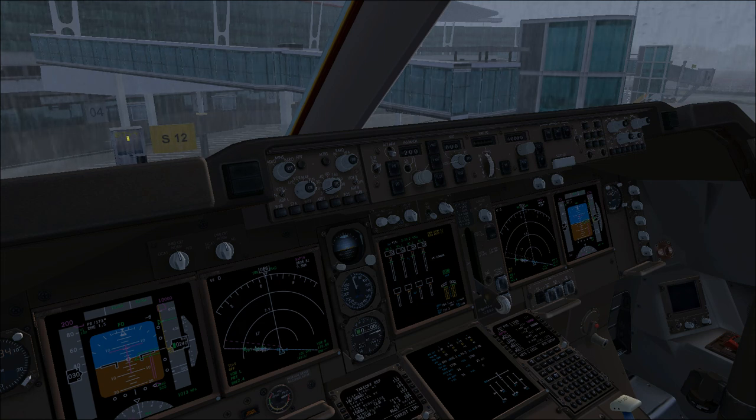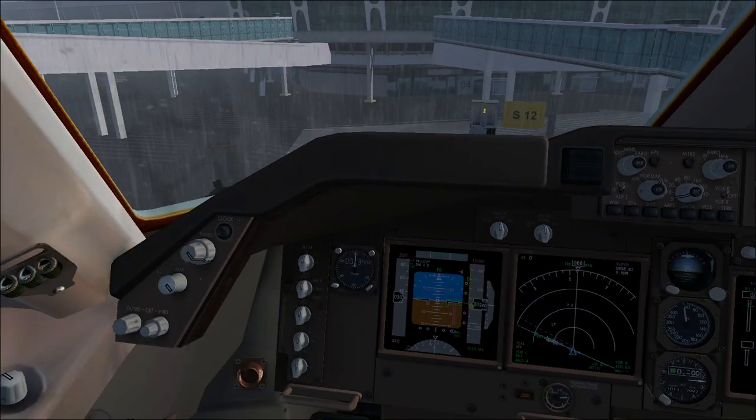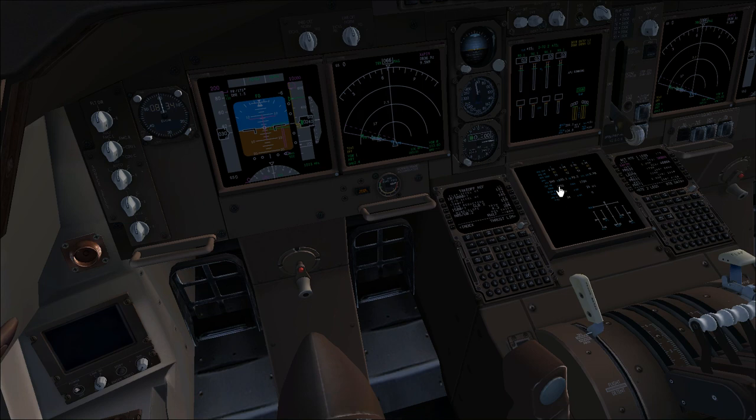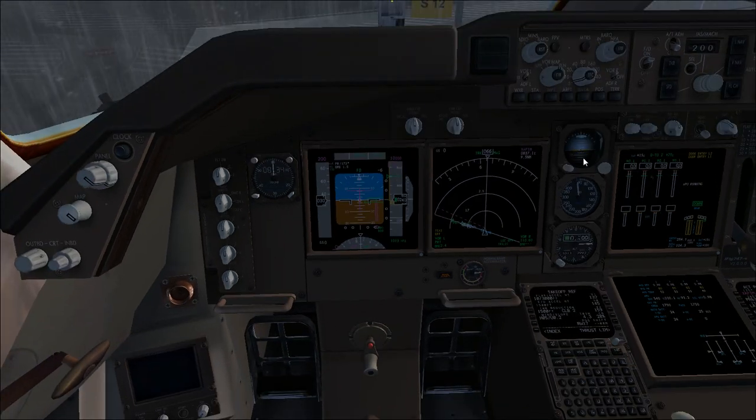At this point, you should check out the oxygen mask here, and do the testing of the oxygen mask and check out the oxygen pressure. That is fine. So crew and passenger oxygen pressure is checked on ECAS, the pressure is adequate, and then we can go to the source select panel. Source select panel, we have to check out that all the sources are on the left. In this case, it's pretty easy because you have to have all of them in vertical. You have flight director on the left side, FMC left, EU is in auto position, IRS is in left, and air data computer is the left one.